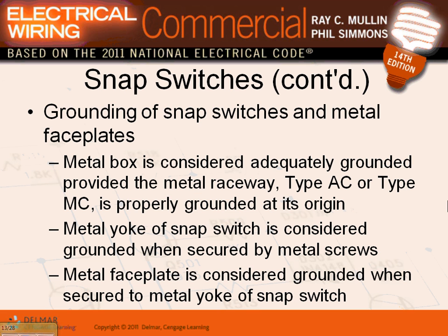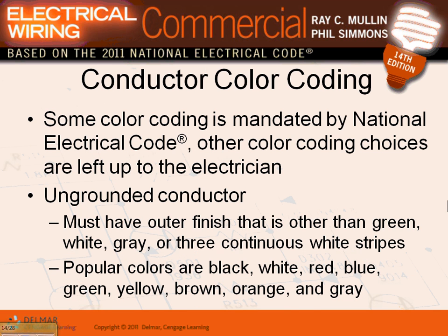That's a whole different story. If it's a non-isolated ground receptacle, by landing the switch on a box like this one, with two screws attached to it, that will qualify. It's already grounded. And the cover for it, if it's metallic, is already grounded because it's attached to the metal. Metal to metal through two screws, grounded. That's what they're talking about, guys. You don't have to pull another equipment grounded conductor. The metal face is grounded through the switch.